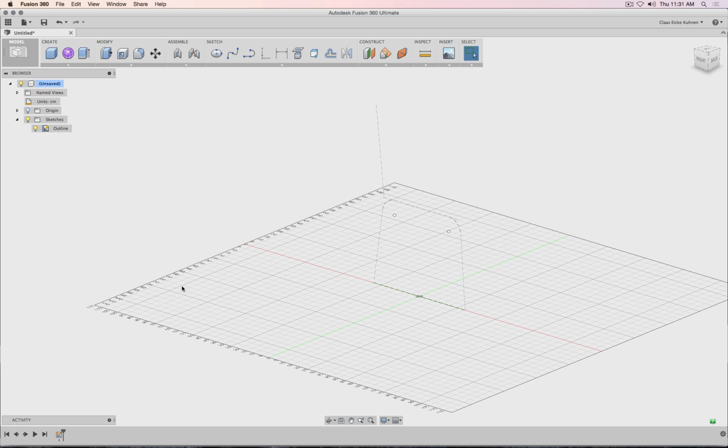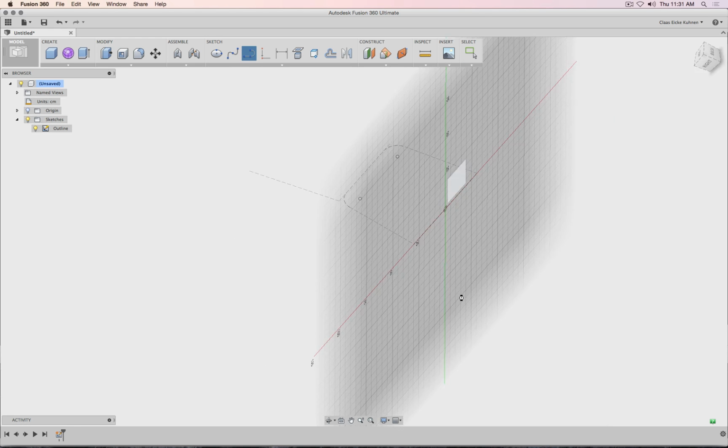So in the next step, I'm going to create a new sketch, and there are of course multiple strategies how you can do it. I could create a plane that is slightly at an angle, project most of this onto. I actually would rather like to have more the approach of a three-dimensional sketch, for which the construction planes aren't really that useful. So I will actually create a sketch on simply the ground plane. So create line, sketch here.